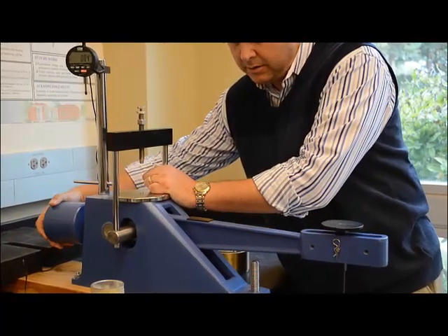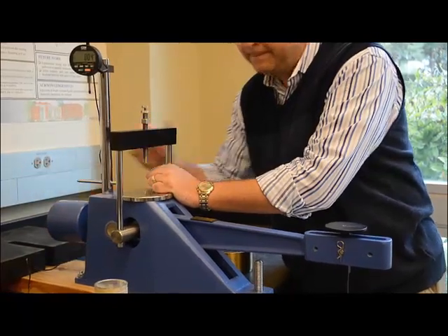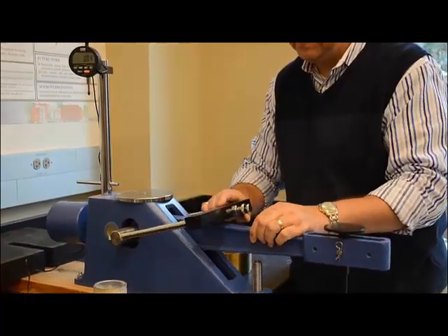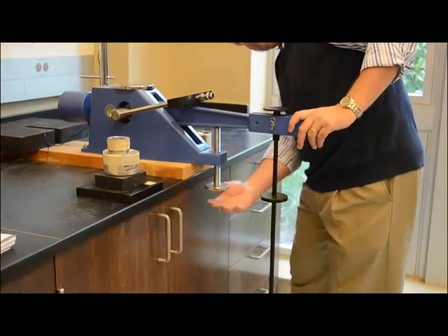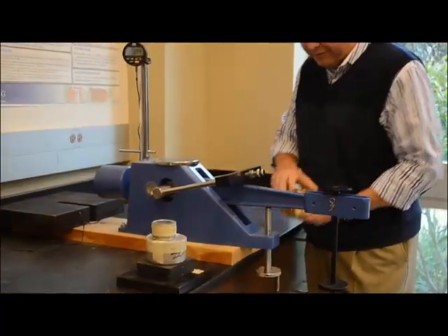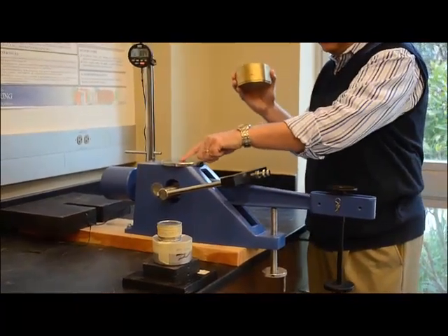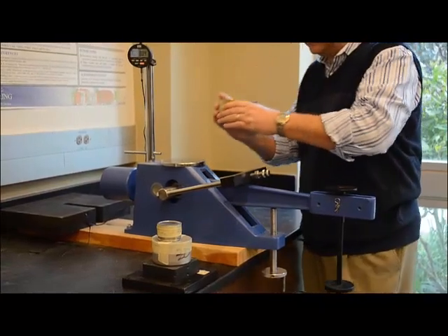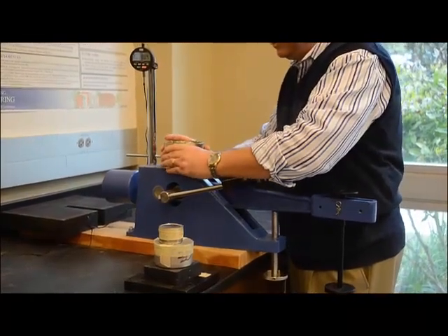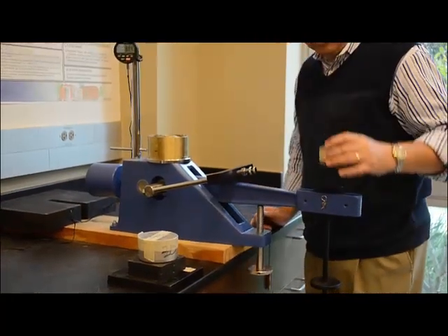Okay, and most of these should be pretty close. Notice there are 3 holes where that hanger can be located. The closest one is 9-to-1, then a 10-to-1 and an 11-to-1 ratio for a 2.5 inch diameter sample. Once we have that all calibrated, there's another nipple on the platform. The bottom of that water bath fits in properly right there to center everything. I have a small weight.